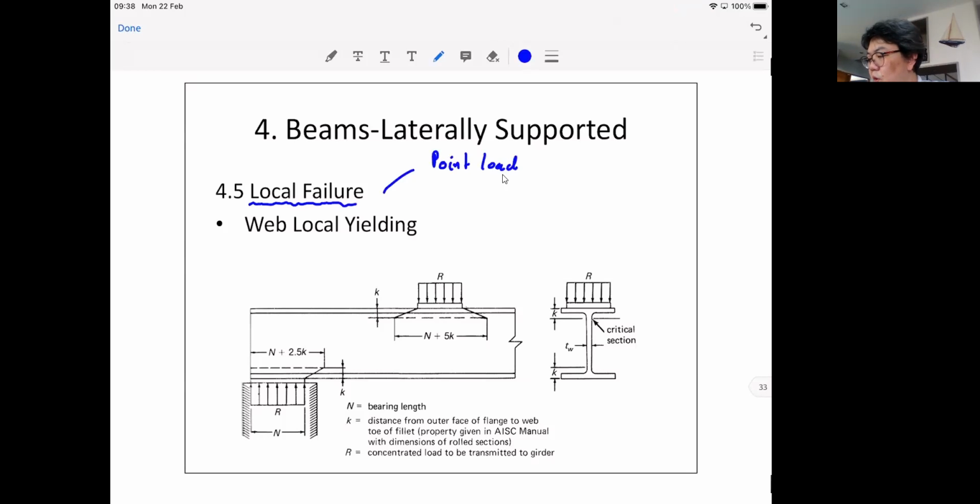But to call it with the true name, it's very, very long and it's very hard to pronounce. So that's why it becomes point load. But make no mistakes, there's no such thing as a true point load. Its official name is called concentrated load, okay? You can call it point load, but in your mind, you must know that even though we call it a point load, it has dimension.